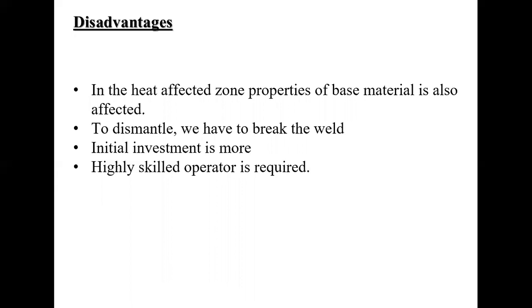In case of bridges, we don't prefer welding; we prefer rivet joints, because if we want to repair any section of a bridge, then we have to break it to dismantle and repair. Without breaking we cannot repair that section. But a rivet joint is a semi-permanent joint, so we can easily repair it. Another reason to use rivet joints is vibration. Welds cannot take vibration, but rivet joints can take the vibration of the entire bridge.